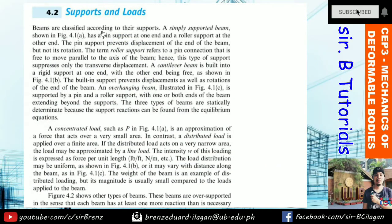So this time we are going to discuss naman or tackle the support and load. So beams are classified according to their support. So we have a simply supported beam which is shown in figure 4.1a. So this has a pin support at one end and a roller support at the other end. The pin support prevents displacement of the end of the beam but not its rotation.